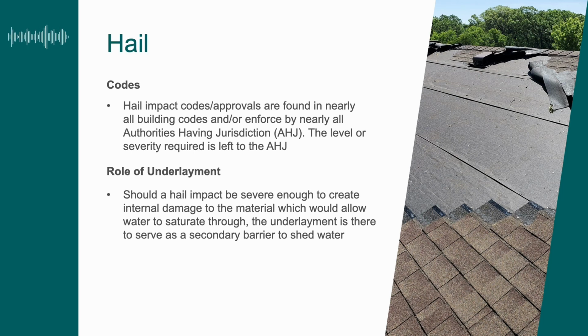The role of the underlayment is critical. For example, here in Texas, hail damage can damage product to some degree, and if it's not noticed for years, you could get some saturation through that roof covering because the compound was compromised. If there's no underlayment underneath and it's not in good shape, you could wind up having leaks in the building. They can't stress enough how important it is to make sure that the underlayment is serving a bigger function than just keeping the wood tight until you put a roof covering on.